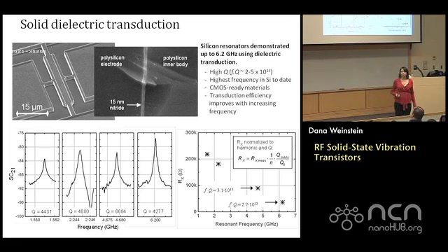So that's all well and good for studying these devices, but in terms of getting a self-sustaining oscillator with small footprint and low power consumption, built in CMOS and used as, say, a clock, well, I really don't want to require an LO in order to make my oscillator in the first place. So I really need a way to do 2-port measurement, RF in, RF out, for these kinds of resonators. Right? So what we need is to change the way we sense the vibrations in the structure. So we need to decouple this input electrically from the output.